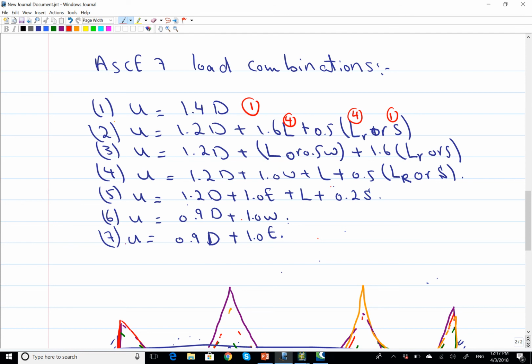So actually, you're going to combine those together, okay? So it's 4. You have 4 combinations here, multiplied by 5. So this one actually contains 20 load combinations, combined together, 20 different permutations. You understand what I'm saying over here? You have 2 bases, 1 to 6 and 1 to 6, okay? This is the first base, this is the second base. This one can take load case 1, 2, 3, or 4. This part can take 1 or 2 or 3 or 4 or 5. You just have those different permutations that you have to model.